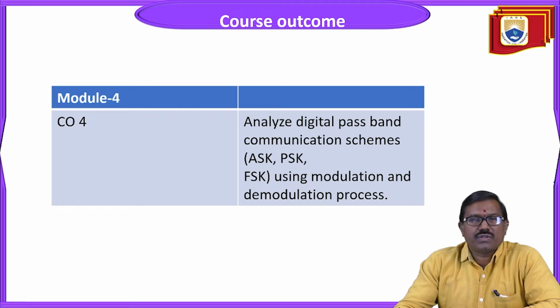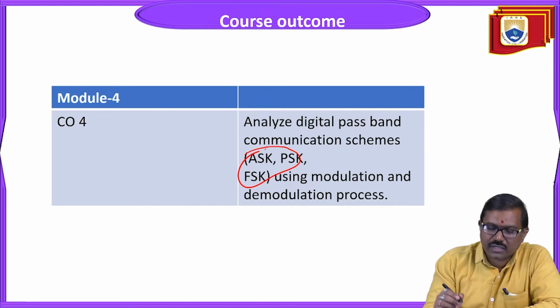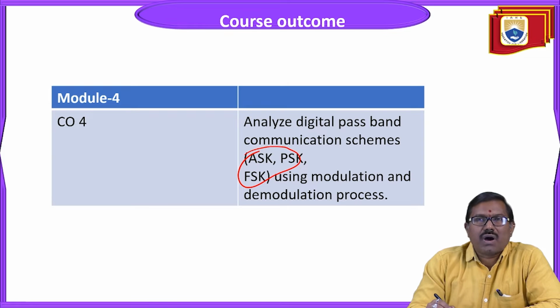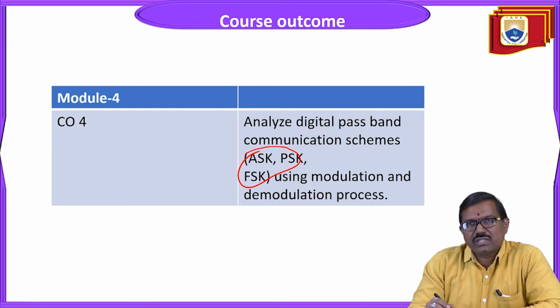Baseband means the original message signal, which is not suitable for a radio link. So we convert this baseband signal into passband form by modulating. In that modulation we have binary and M-ary. ASK, PSK and FSK can be called binary modulation techniques, whereas QPSK is a simple form of M-ary.